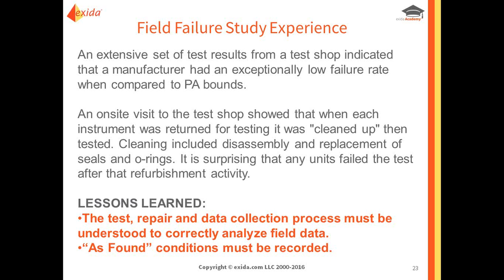So what do we learn? If you want true failure rates, the test information, the repair information, and the data collection process must be understood to correctly analyze field data. They just didn't specify what their definition of a failure was, and this is why you need to be very clear. You need to do as found conditions; those have to be recorded.